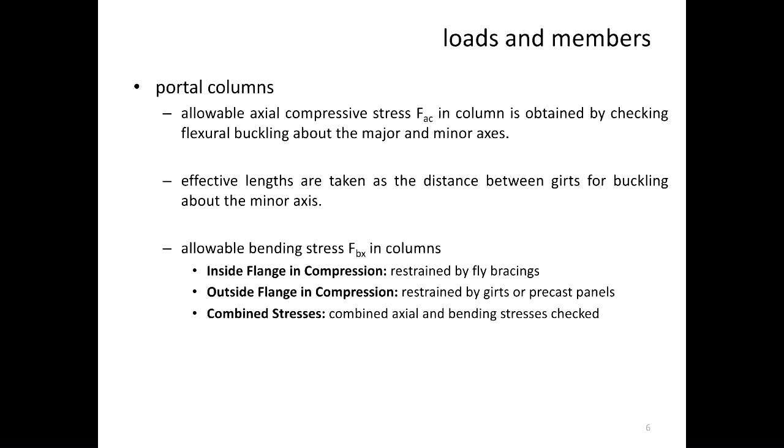Okay, so when we're doing the check, you have to check mainly what will happen when you have a taller element, not a structure, a taller element like a column, and you have a lot of wind pressure. It's likely to fail by buckling. Because it's too tall compared to its width, it's slender, so it's likely to fail by just easily bending like that.